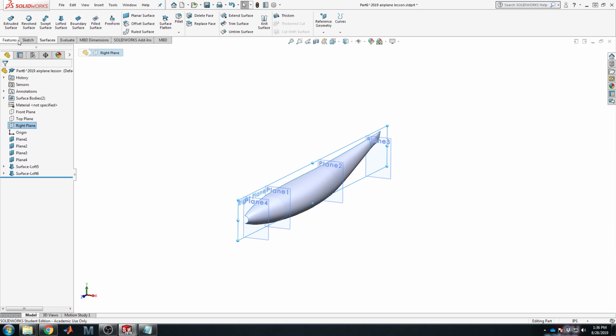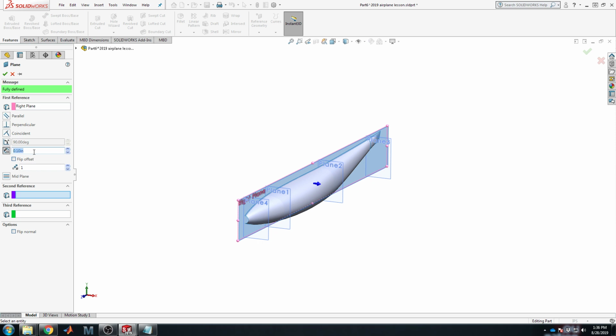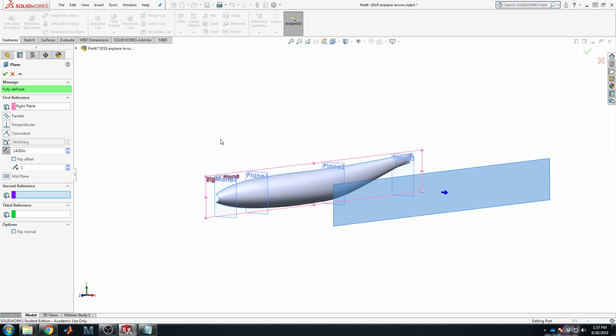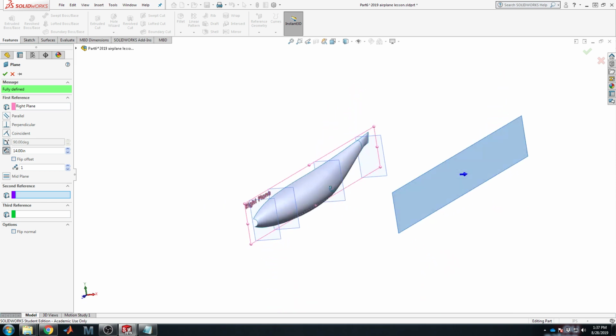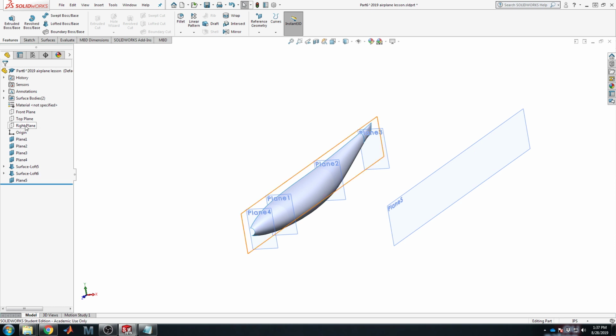So I want to then go and create another plane offset from that center line out some distance. And of course, this is where the entire design process of an aircraft comes from. Let's go out something pretty far, 24 inches. Now, if you're saying, well, isn't this exactly like the other video you made, Dr. Hayes? Yes, it is. But this time we're actually going to be doing a tail and other things and building this up for the reasons of lofting and smoothing an entire aircraft and the joints and everything between them. Okay, so we'll put that 14 inches out. That'll be a 28-inch span wing, which for the vehicle's design and competition that we're kind of basing this off of, that's entirely a reasonable size.